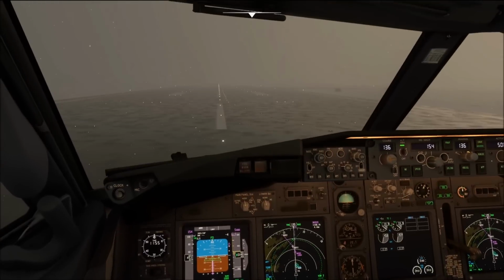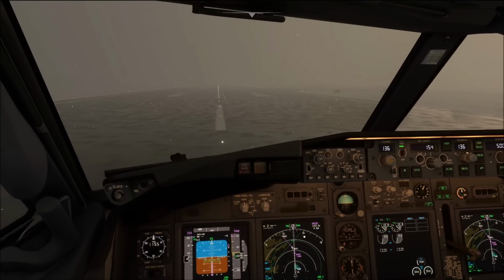So, let's say for example, when you're at the holding point, ATC clears you to line up, then you are going to tell them something like, PMDG 737, line up runway 1 left, we will need 30 seconds on the runway for ice shedding. And it may be that ATC cancels your line-up clearance for that, in case arriving traffic is too close already. So, with all of that said, let's go ahead.